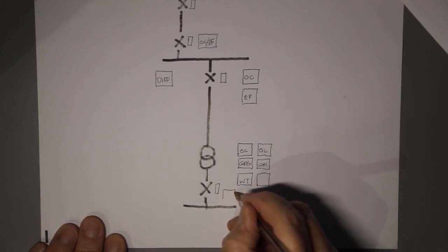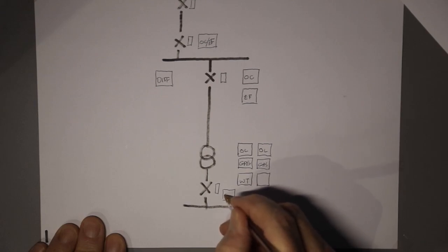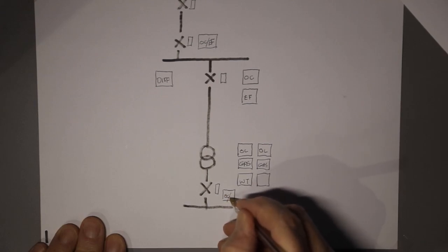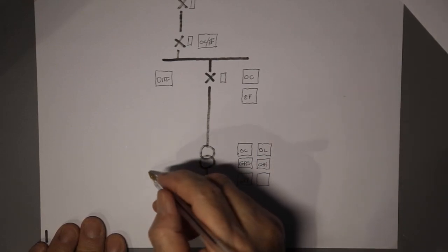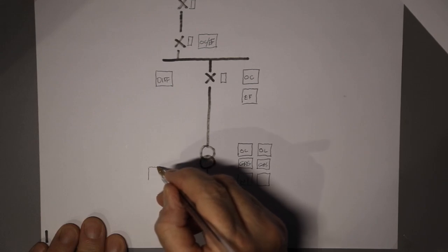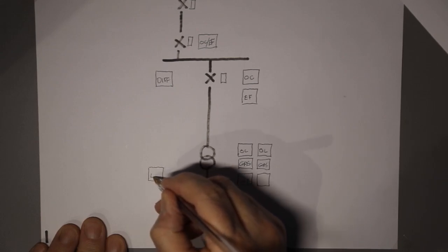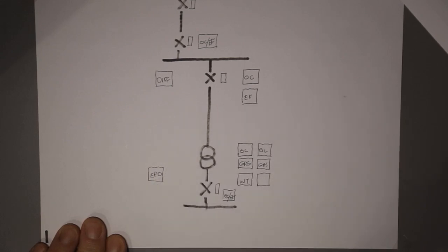The low voltage ACB will also have a shunt trip coil built in with overcurrent, probably all as a single unit that manifests itself as something like a Micrologic relay. Another typical item on site is an emergency push button.